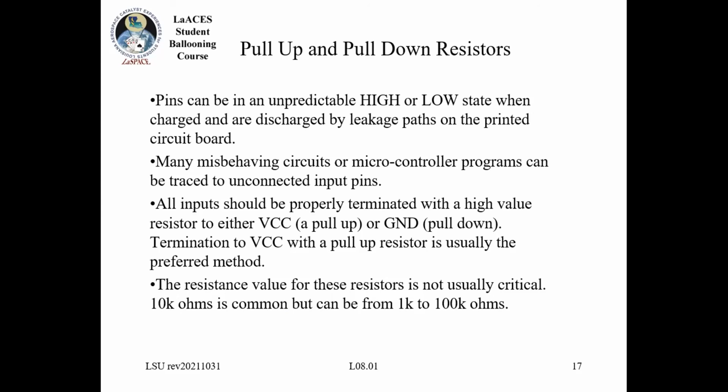If that time constant gets to be large compared to the length of my signal pulses, well, now my nice square waves will start to get rounded off, and I may not be all the way up to the positive value by the time the pulse is over.